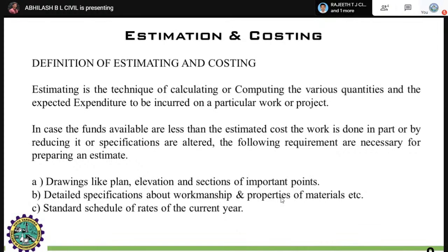In the bill of quantities, you can see n number of rows and columns, which consist of a serial number, description, quantities, and per unit cost for a particular material, either per piece or per square meter or per cubic meter, based on the type of material you are going to procure.